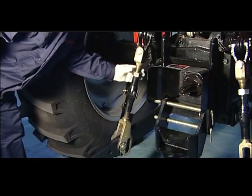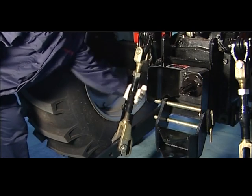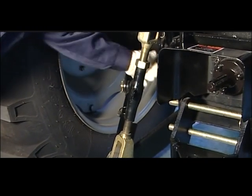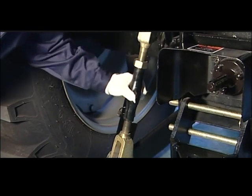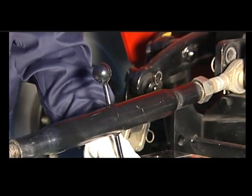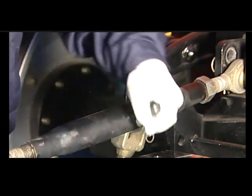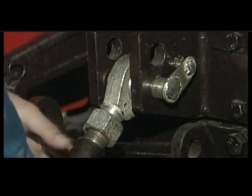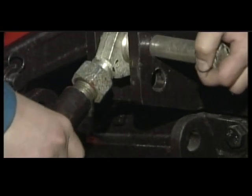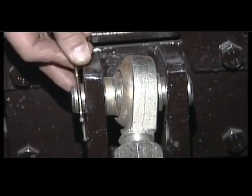Lifting lever. Generally, the length of lifting lever shall be adjusted at medium length. The purpose of adjusting the lifting lever is to adjust the lateral horizontal position of the tool. Upper pull lever. The length adjustment of the upper pull lever is mainly to adjust the longitudinal horizontal position of the tool. There are 2 holes connecting with the base for use. A suitable location can be chosen according to the tool column height.